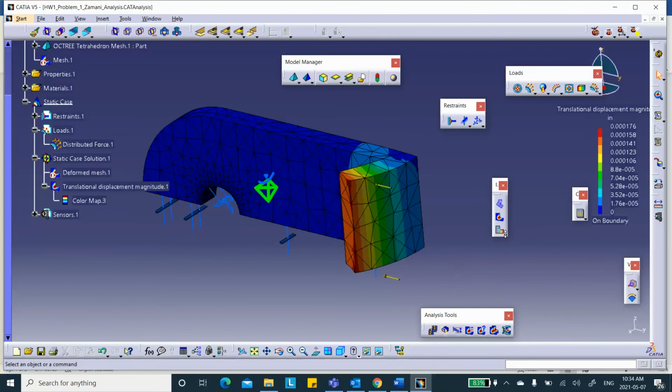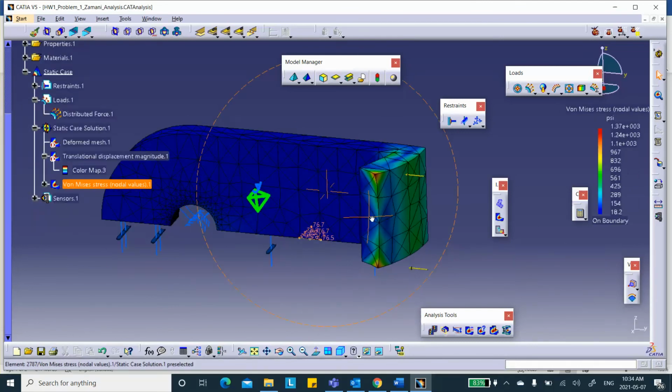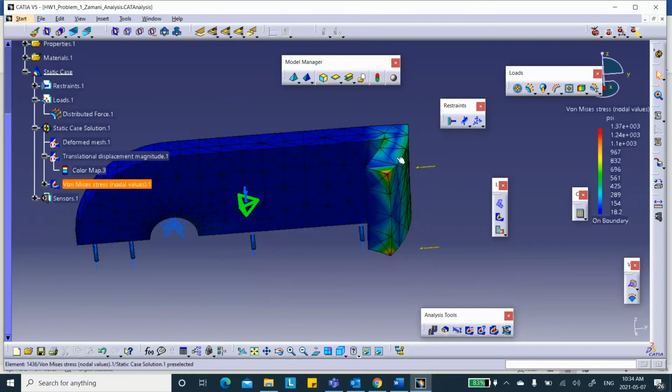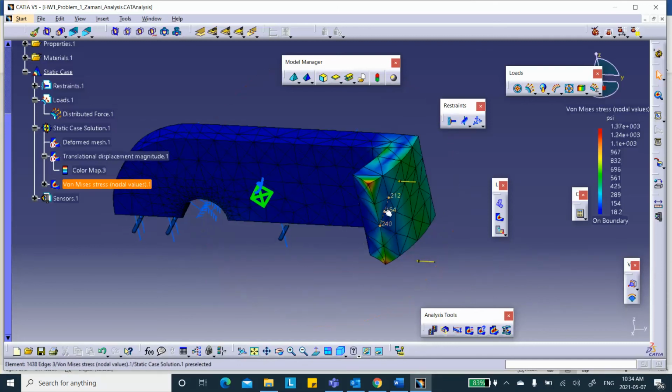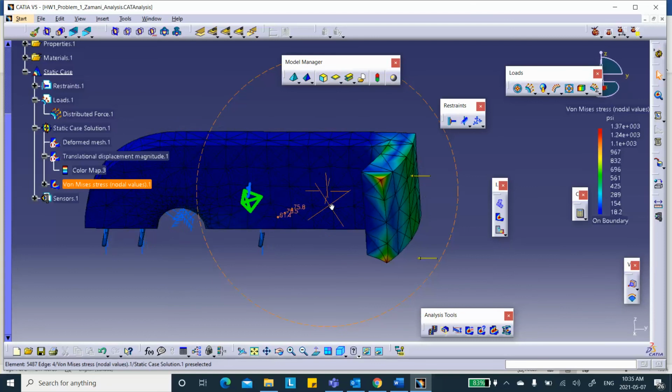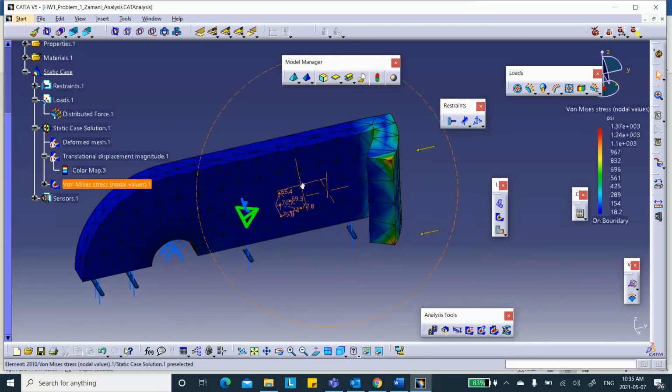Okay, let's look at the stress, von Mises stress. Now that doesn't surprise you because this looks like a cantilever beam, and the cantilever beam has the biggest stress when you bend it around the root right there. Now, if you say, well, wait a minute, what are these things? These are unrealistic stresses because you're applying unrealistic forces. How do you apply an edge force? It's impossible. It's like putting a knife there and pressing on the knife. So, yes, these are unrealistic. This is garbage, but you know how to do the problem if you're asked to do it.